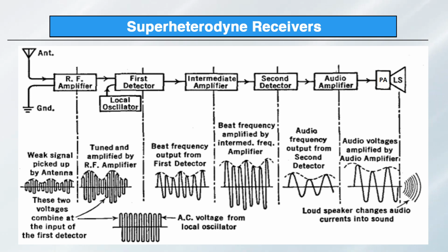The characteristics: it operates at the intermediate frequency determined by the mixer stage, and typically includes multiple stages of amplification to achieve the required gain. Design considerations: it must have high gain, low noise figure and good linearity to preserve signal integrity, often using tuned circuits to select the desired IF frequency and reject out-of-band signals.